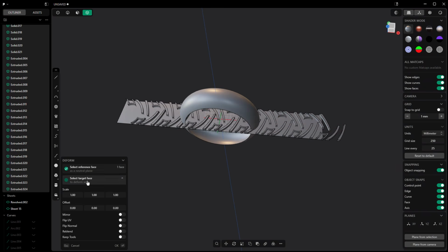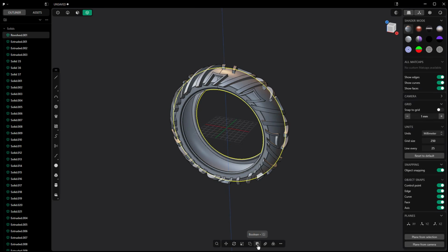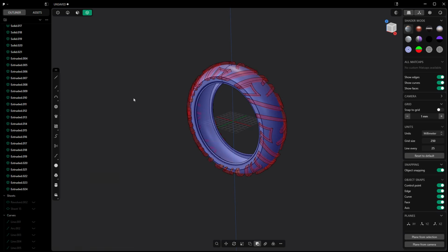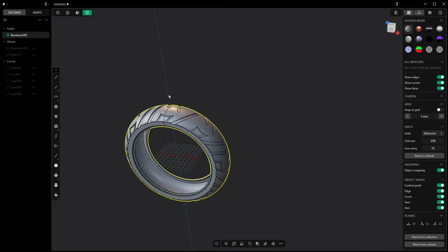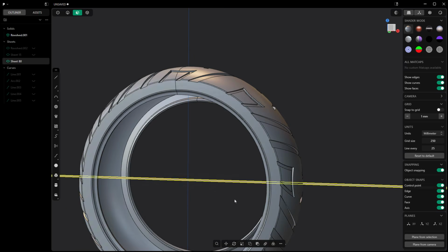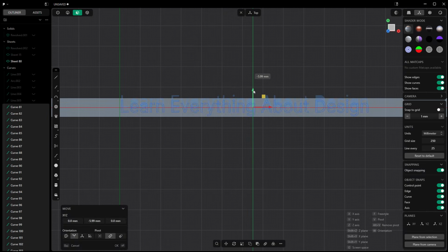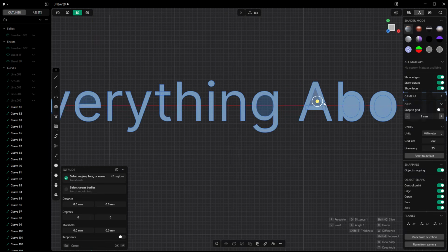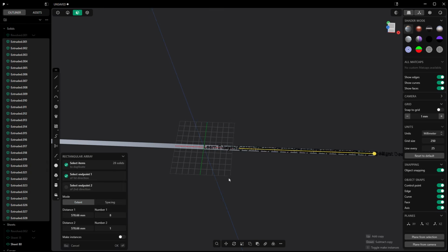Today's video is about creating a motorcycle tire in Plasticity. There are a handful of tools we're going to be using. Specifically, we're going to create curves and use revolve. We are also going to create a revolved sheet, or a surface, that's going to be the extent or the place where we're creating our actual cutouts for the tread. We are going to be using Unwrap and Deform, and with all of these, as well as things like patterning, we're going to build out a pretty realistic looking tire.